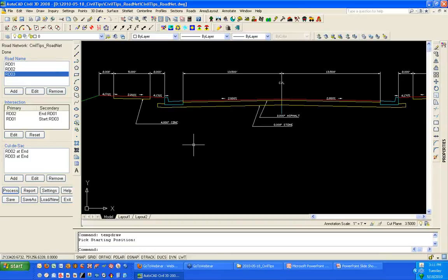So knowing that that's how I used to do it and how it's still typically done, this is a pretty powerful little tool, because for those engineers, those people that have to sign off on this, if you go to this Draw Typical Template command and pull it from the road network file that you've been working with, you are assured if this comes in wrong, you know that that design is wrong.